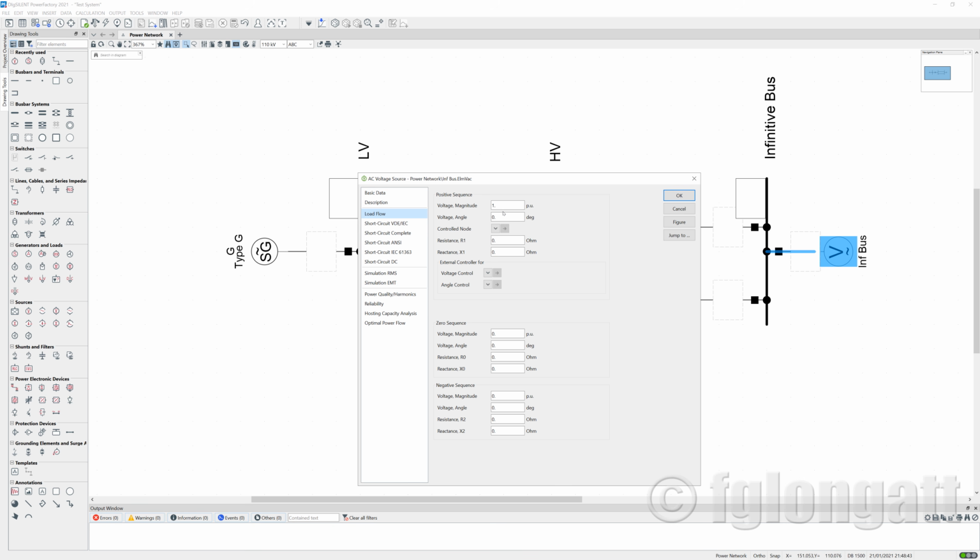If you remember from the presentation, we said that the voltage at the infinity busbar is magnitude 1 per unit. And that value is located here. What I'm telling you is that this infinity busbar is already set to 1 per unit, and nobody said anything about the angle, but I will assume, as usual, that the infinity busbar can be defined as the reference busbar.